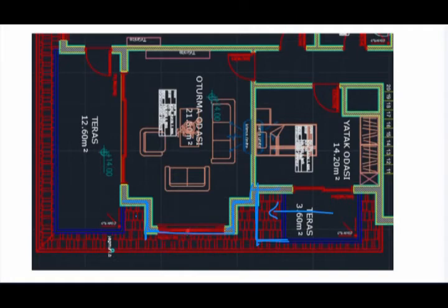Some of you in the project, if you are working with a gable roof, we want to see that 45-degree line, let's say, if it is like that or if it is flat, it depends on you, as a dash line. So the roof plan in the duplex second floor plan, we need to see the lines, how they are working. Very light, so it will be understandable, and we will understand the overall structure. So if you are working with a duplex floor plan, please put those dashed lines in your plan.